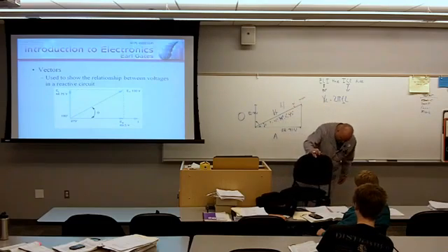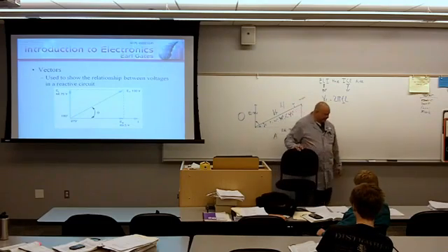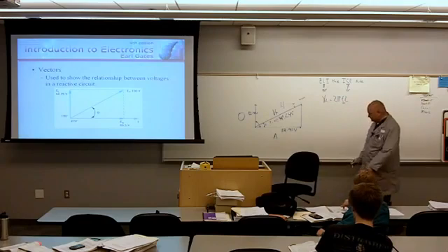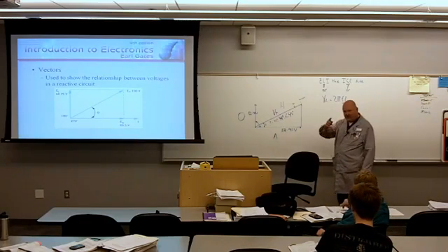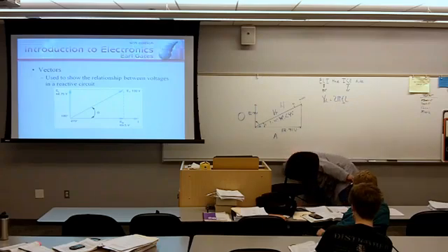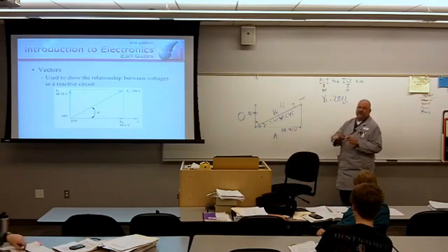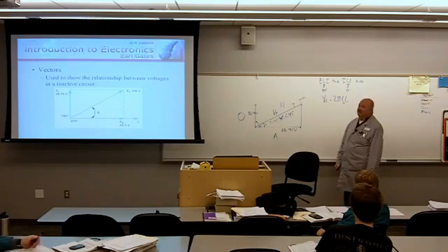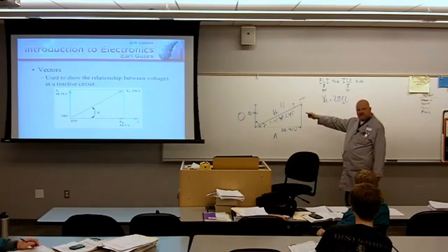In a series circuit is what? It's a voltage divider, right? The answer is not 20. 10 plus 10 does not equal 20 in a series AC circuit. It's going to be something more than 10, but something less than 20. And I guarantee you on a multiple choice test, only one answer will be correct. So don't get suckered in that one. So does this make sense?